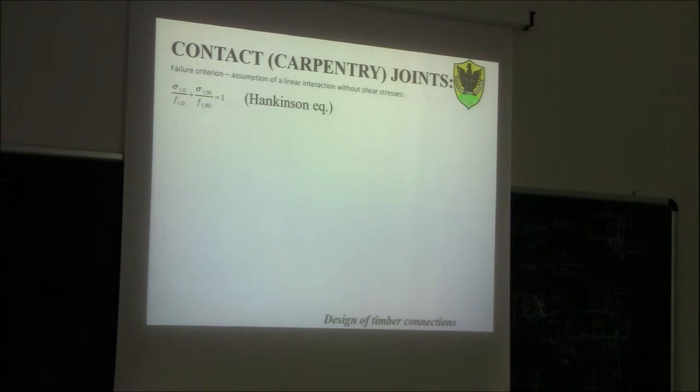stresses in this way. So those stresses, so this is the grain. Those stresses have one component parallel to the grain and one component perpendicular to the grain. So we have, let's say, a sigma T0, stress parallel to the grain, and sigma T90, stress perpendicular to the grain.